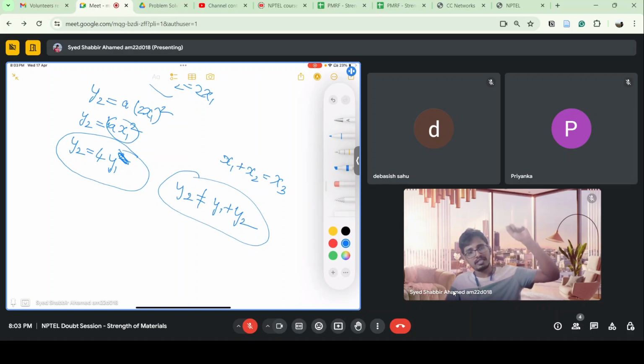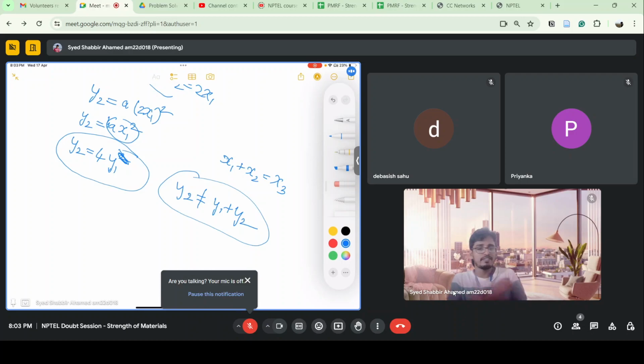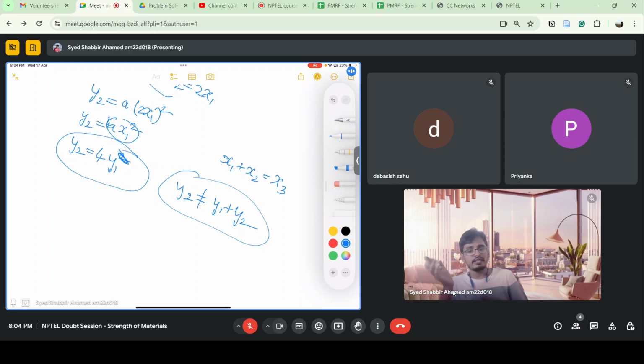Plastic zones, like if you have a rubber material, it is not linear, and also there are viscoelastic materials. They don't have this linear behavior. If you extend a rubber, a lot of deformation happens, like plastic deformation. So some materials do have that, and also biomaterials like skin, arteries, soft materials. A lot of soft materials are there. So there you will get this non-linear elasticity and different things.